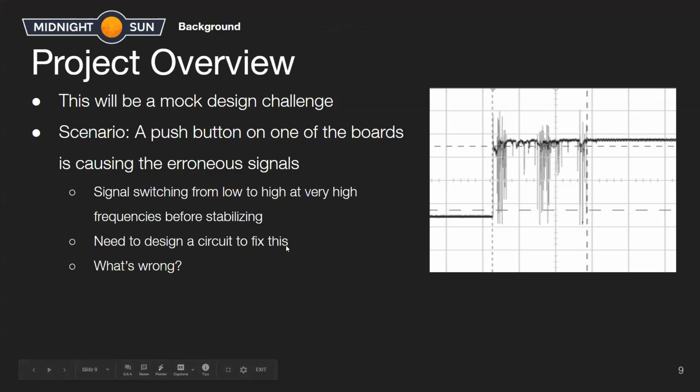Yvonne says it's because of inconsistent contact. Yeah, that's mostly right. For physical buttons, how it connects a circuit is there's 2 metal contacts, and when you press the button, the metal contacts come together. And to us, that just seems like one motion. But as the metal contacts get close, it can actually cause the circuit to connect and disconnect really fast.